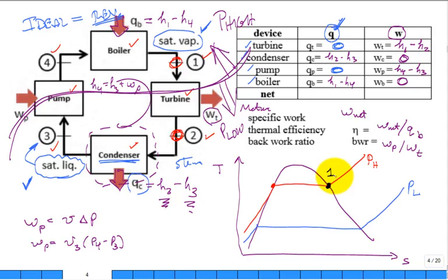No. What property for a reversible adiabatic turbine? It's isentropic expansion of the steam through the turbine, so S out of the turbine is equal to S in. That's why we like the TS diagram. The TS diagram helps us model exactly what's going on with the second law. And in the second law analysis of that turbine, S2 is equal to S1.